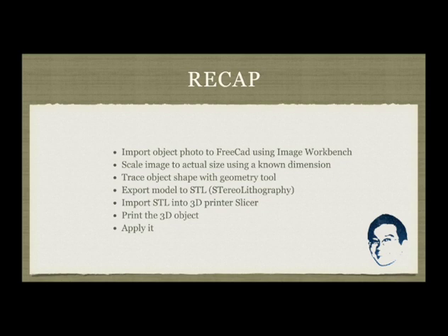When the sketch is done, we use the Pad tool in the Part Design Workbench to create the thickness of the object we want and use the Feather tool to smoothen the edges of the pad. Once the 3D model is completed, we export it to the STL format that can be used in the 3D printer slicer software to slice it for 3D printing. Finally, with the printed outsole, we fit them onto the shoe with the laminated plastic adhesive.